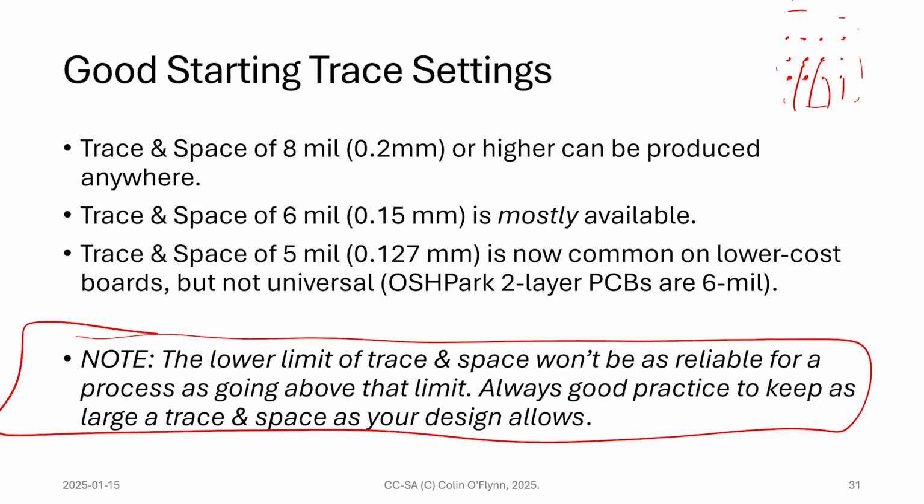Outside of that, I basically set a design rule that says use the narrow, expensive, super close trace and space in there. Outside of that, go to a wider trace and space because I have lots of room. I only need it in that one spot. So it's good practice if you can do that, to give the fab the most chance of success.